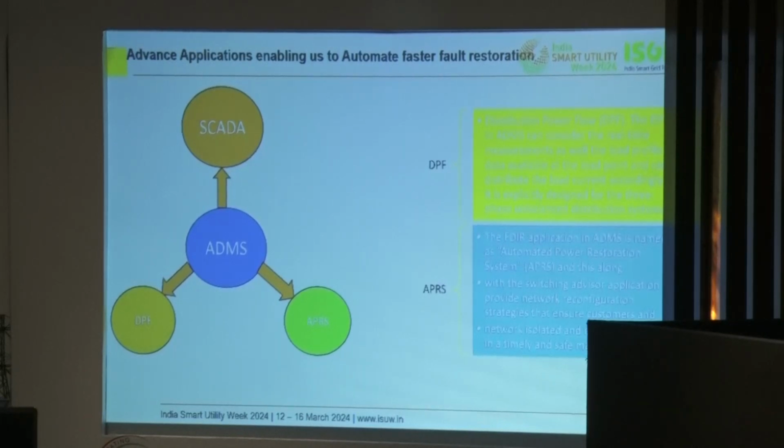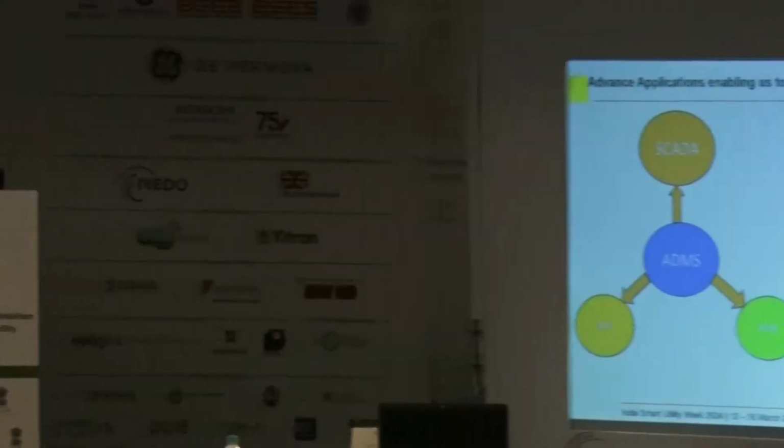Along with that, we have the customer data as well, like data of our DTs, and how much sanctioned load is connected to particular DTs in our distribution areas. By merging those data, we take GIS as a reference for collecting data like the types of cable, whether underground or overhead, and the impedance of those cables. This system gives us the overall load that can be running on these DTs or these consumers without having SCADA devices connected to them. Based on the SCADA value at a higher level, and on the consumer segments at a lower level, the distribution power flow module gives us the data.